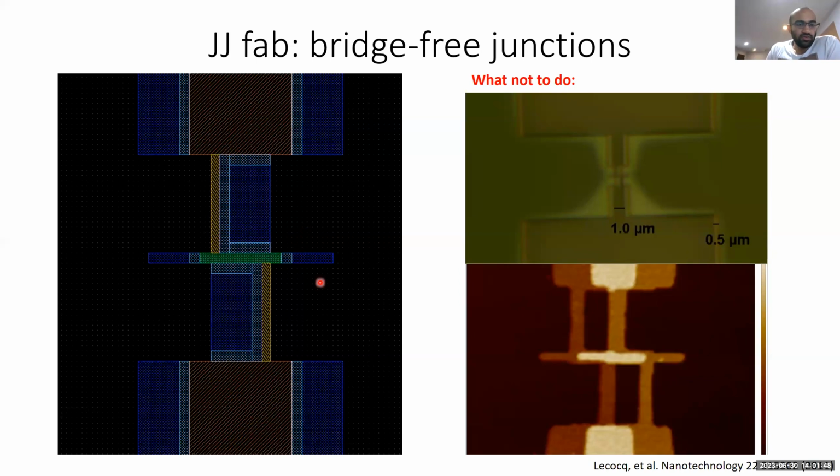And so you can quickly see that because of the large number of different doses to keep track of, to actually do this correctly, you need to calibrate a larger number of doses. And if you do it incorrectly, you'll end up with something that looks like this. You see there's this region that's shaded a little lighter color. This is actually a natural undercut that's formed by a proximity effect.